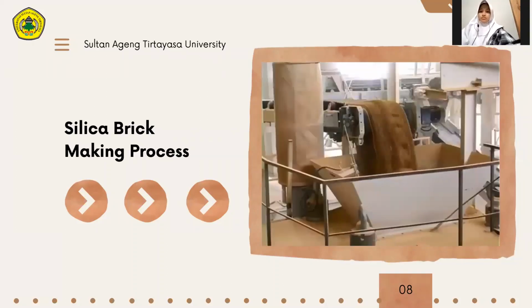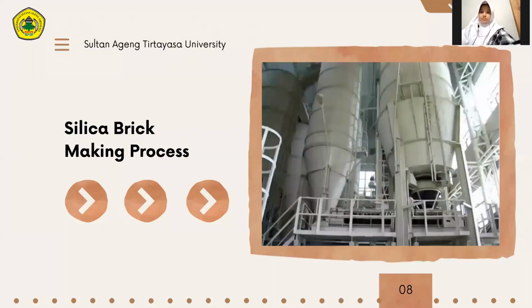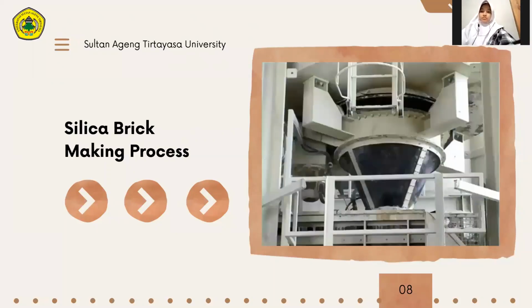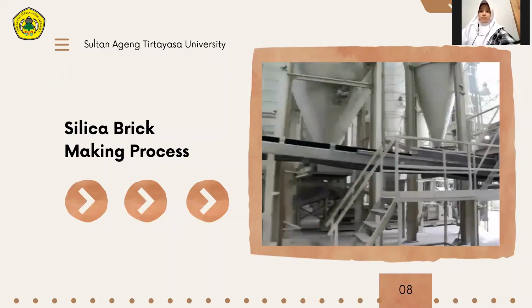Water can be added if necessary for additional moistening of mass. Mixing process occurs automatically in a twin-shaft mixer for mass preparation. Then the sand lime mass goes to reactor.